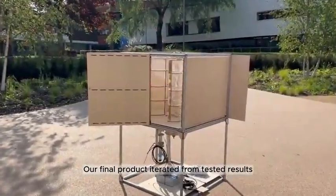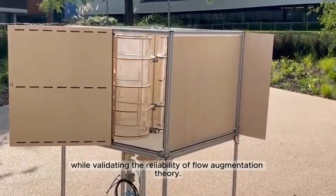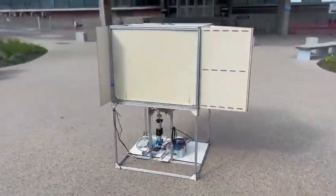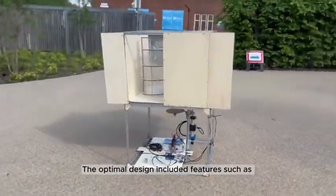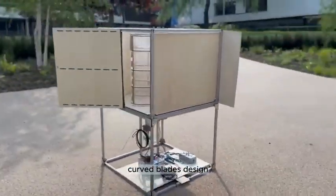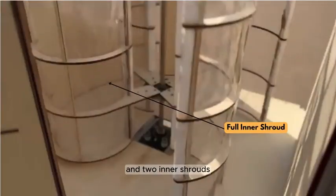Our final product is iterated from the tested results, combining features that deliver the optimal performance while validating the reliability of flow augmentation theory. The optimal design included features such as two 20 cm long back separators, curved blade design, a wedge with 45°, and two inner shrouds.